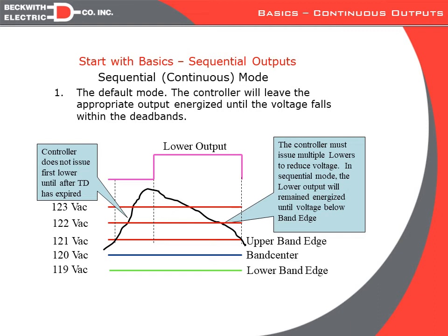And it takes a while for a regulator control to measure the voltage, determine if it's out of band, get up the physical output, drive the regulator. It also takes a little bit of time in reverse to measure the new voltage after a tap, verify whether it's in band or not, and then make the determination as to whether to keep the output up or not. Now, traditionally, regulators and LTCs have taken anywhere from 1.5 seconds to 6, 7, even 8 to 10 seconds for them to mechanically, physically operate 1 tap. So there was no issue in the regulator control taking a little bit of time to verify the voltages and determine whether to take the output off or not.